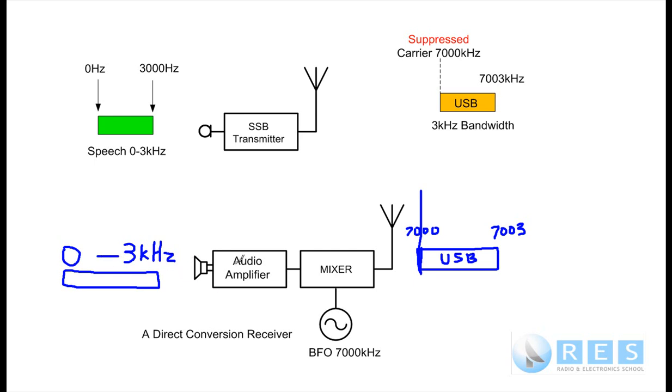that in the speaker. The audio frequency amplifier will not pass any of the other RF mixing products, so we don't have to worry about them. Audio frequency amplifiers only amplify audio frequencies. That's called a direct conversion receiver.